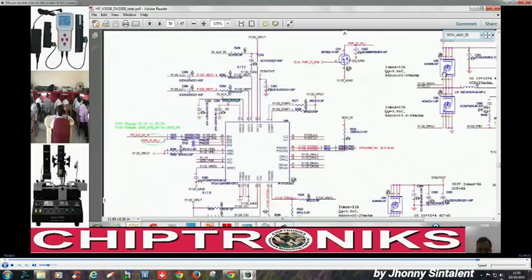You can see this 3D3V_AUX_S5 is generated via this regulated LDO voltage. If this LDO voltage is not coming, then we have to check this 3 volt 5 volt regulator, right?